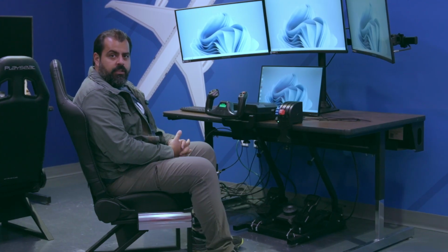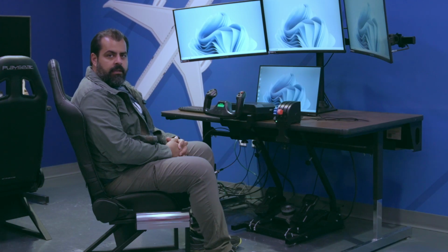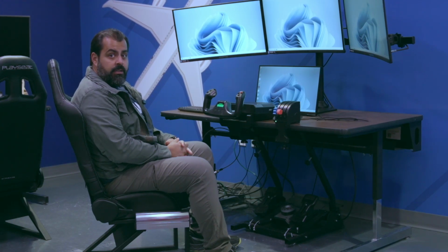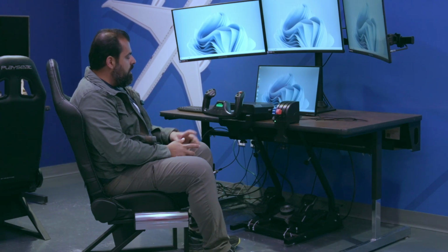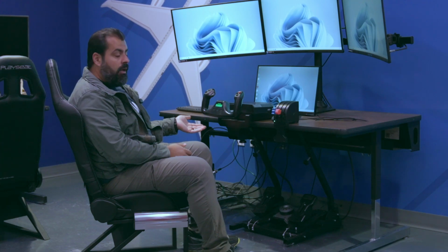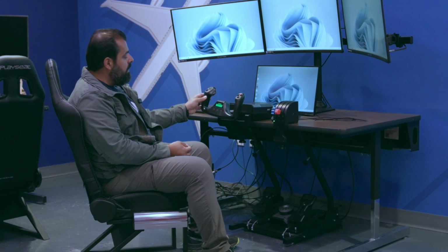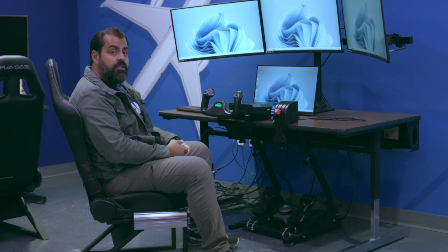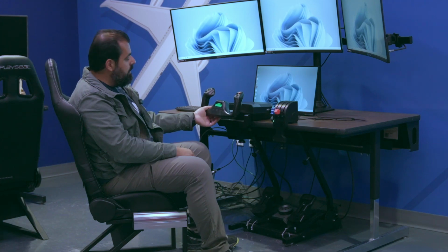Before starting the flight, we need to talk about the flight control systems we have. If you have watched the lecture recording and gone through the lecture notes, you already know what each of these controls are. This is called the yoke. Using the yoke, we control the roll of the aircraft, so turning while you're already flying. And we can also control the pitch of the aircraft, going up and going down. So this will go up, this will go down.